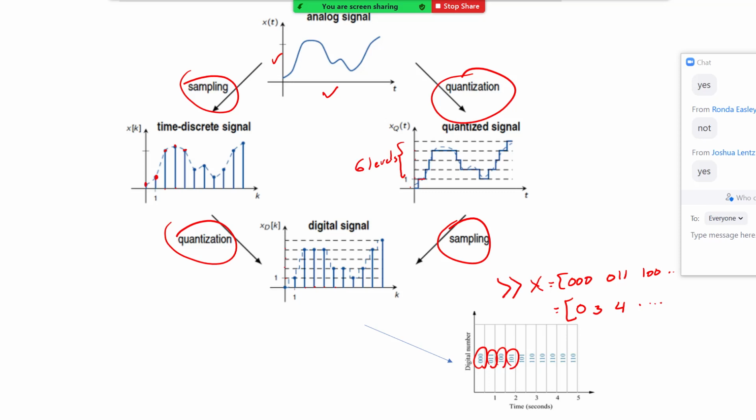So again, Nyquist theorem, keep that in mind. We'll come back to it and refresh on it. But choosing the sampling time, how fast we're going to be taking these samples, is not random, and we have to follow rules in order to ensure the signal can be reconstructed without losing information.